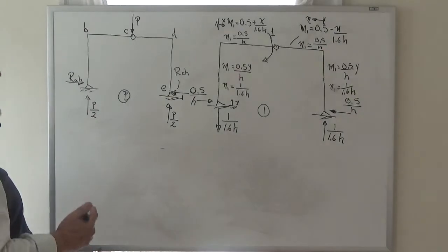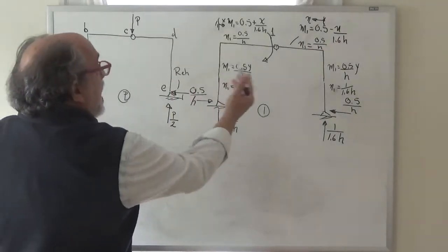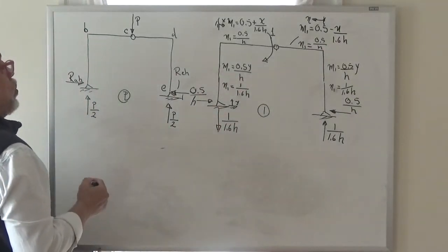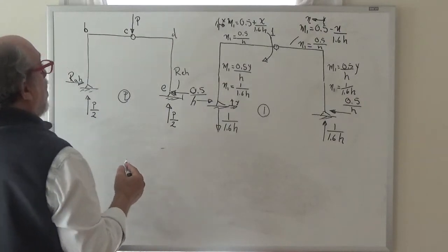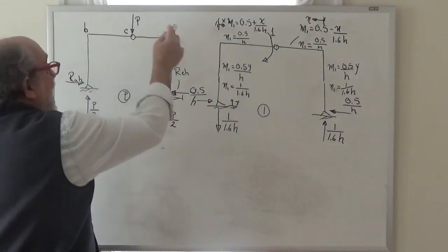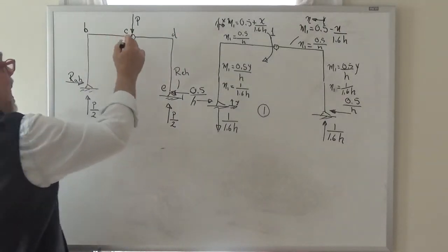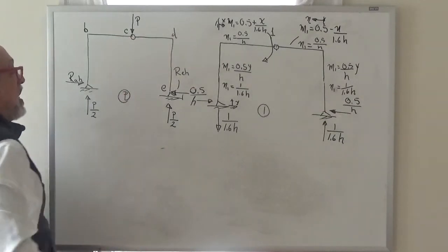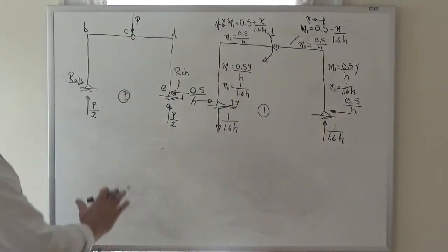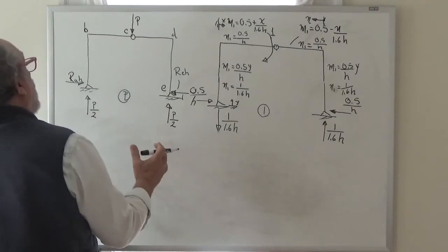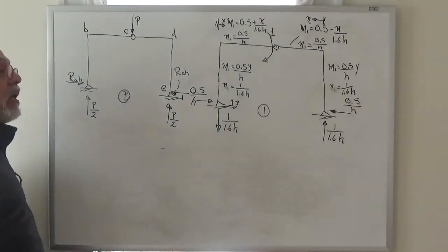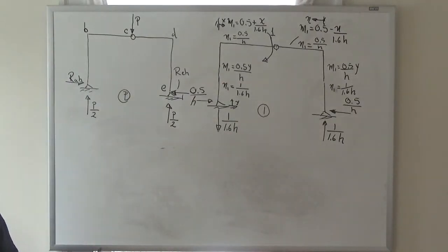We have to, again, come back to the same thing we did previously, which is to take a free body diagram that takes advantage of the fact that we know that point C has no moment. Now comes the issue of where is P, is it to the right or to the left of the hinge? As I said, you can put it on any side you want, but once you decide which side it is, that's the side in which it is.